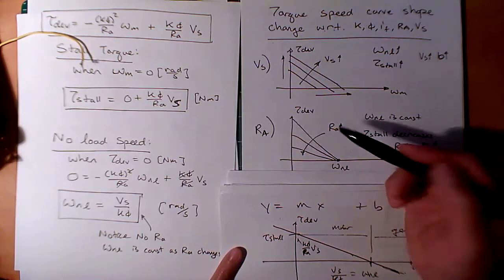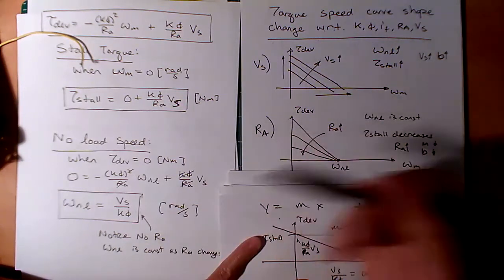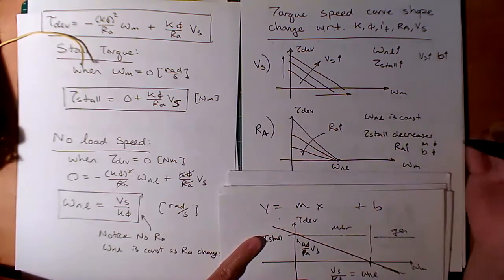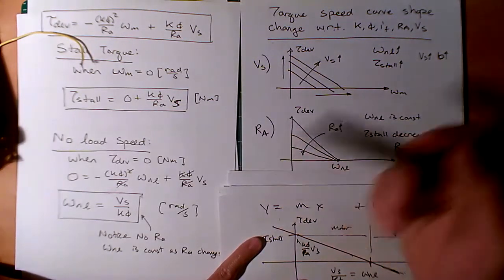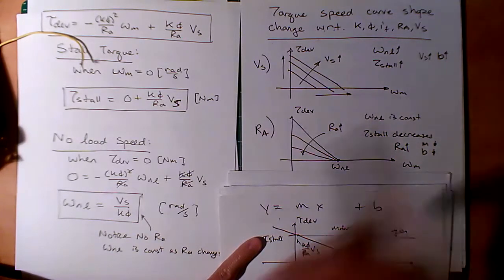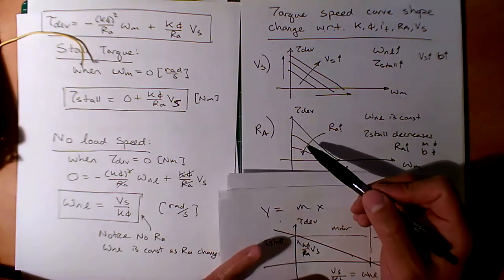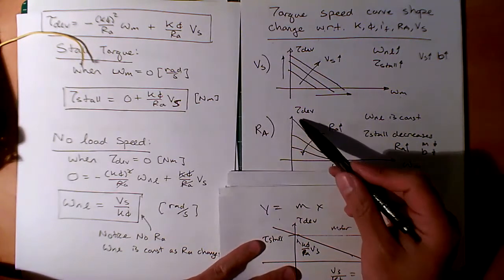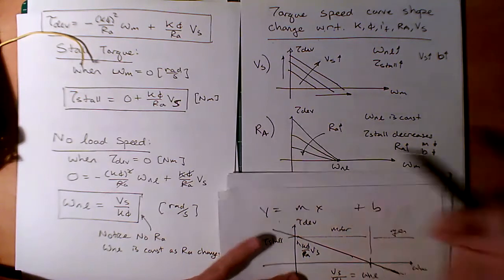How would you physically increase the resistance? Well, let's say you had a motor where you added more turns, or you changed the gauge of the wire such that you have a thinner wire. If you had a thinner wire, you increase the resistance. And if you kept the number of turns the same, then you'd still get the same voltage, right? Or back EMF. But that would be a consequence of using thinner wire, is that your ability to generate torque goes down. Okay, what about flux?